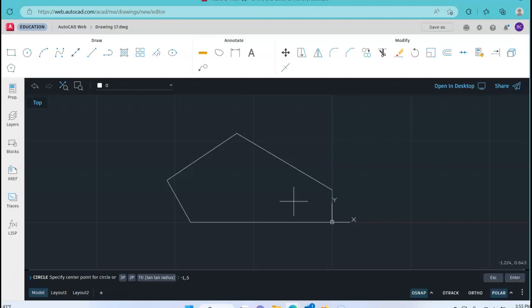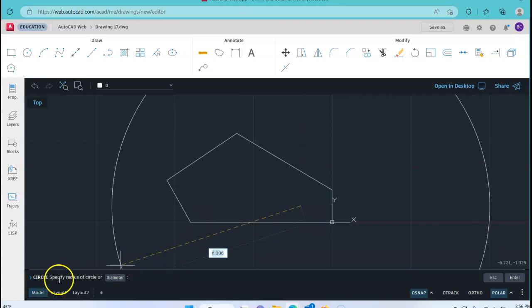So take a look at the lower left-hand corner. Notice the dimension line. Follow over. In the x, it's a 1 inch dimension. Of course, we're going to the left from there, so that's a -1. And we're going up from that point, our x0, y0 datum point. So since we're going up from that point, it's going to be a positive ½ inch, and I can hit enter.